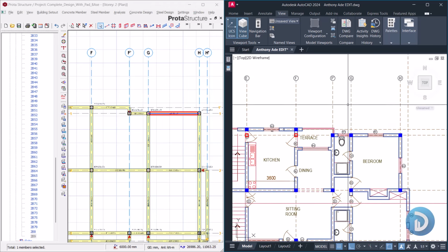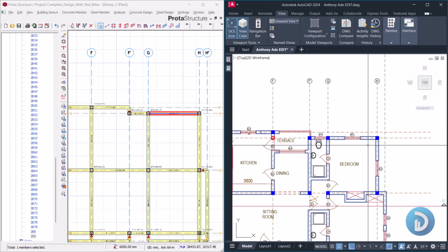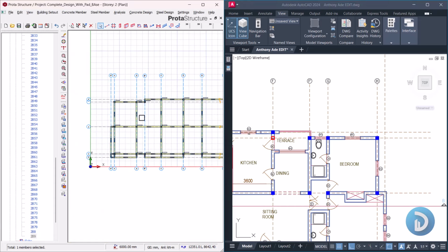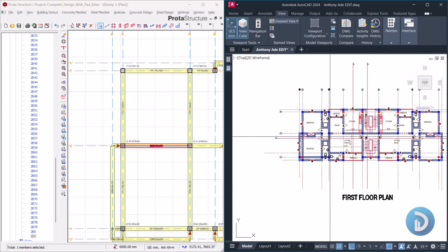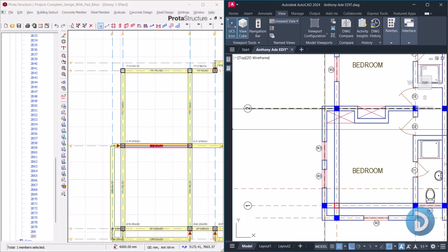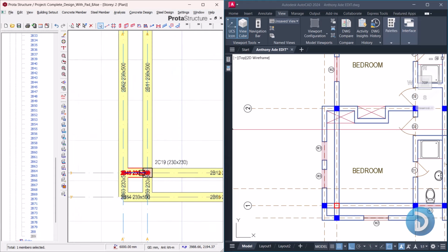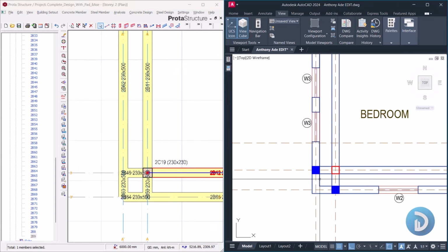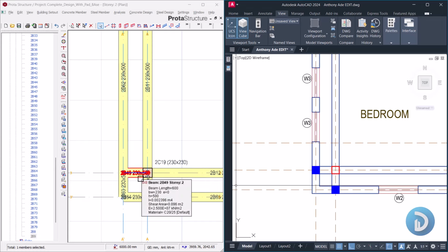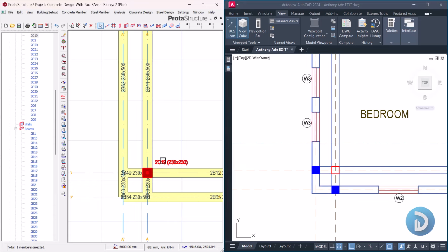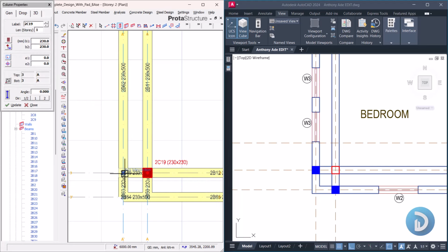For grid line G, we are keeping this column, which is this. Grid line H, we are also keeping this column, which is this. All right, so we also move on to this part. And we said that this part will get to cantilever this beam outside. Okay, so this is okay. We are not touching this. But these columns will be transferred to the left and also be transferred downward. Okay, so the cantilevered beam that we've made from the ground floor level will be able to carry these columns. So let's right click, come to properties, we'll put this here, we also put this here.